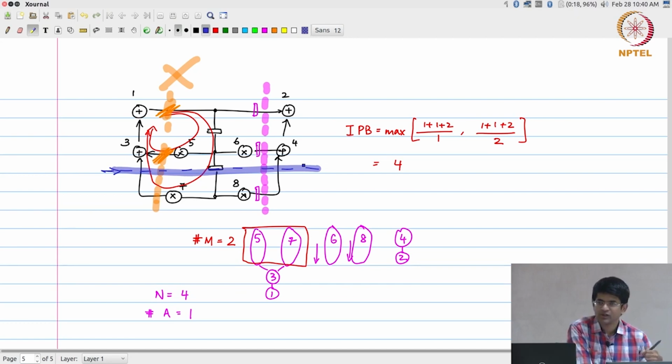So once I have that kind of behavior, it means that it's not a feed forward cut set, but on the other hand, because of the presence of this register over here, I can do a retiming, meaning that I do a -1 on the edges going from top to bottom and a +1 on edges going from bottom to top. What would that look like? It would essentially say add one register here, delete this one, add one register here. Now what have I got?